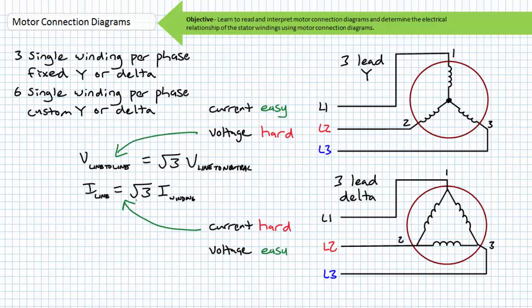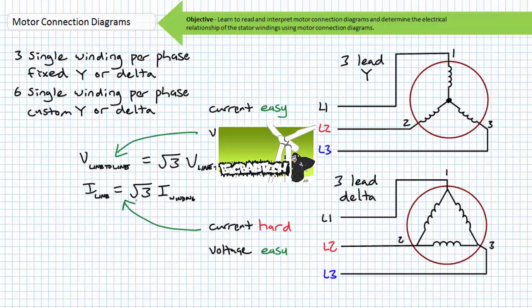This mathematical trickery allows a technician to take easily accessible line-to-line voltage and line current readings external to the motor, regardless if it is Y or delta configured, thereby circumventing invasive and problematic inspection. Lectures on three-phase AC power calculations, available at the Big Bad Tech channel, discuss this cunning trick and more for balanced three-phase AC loads like motors.